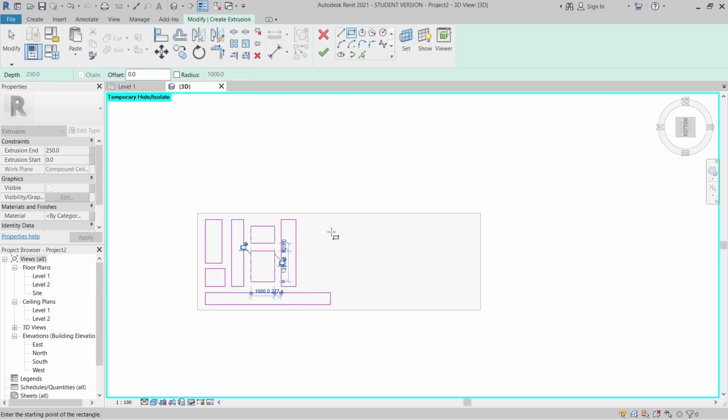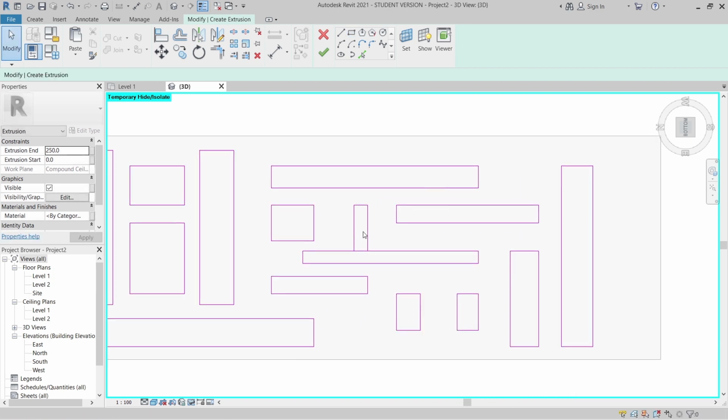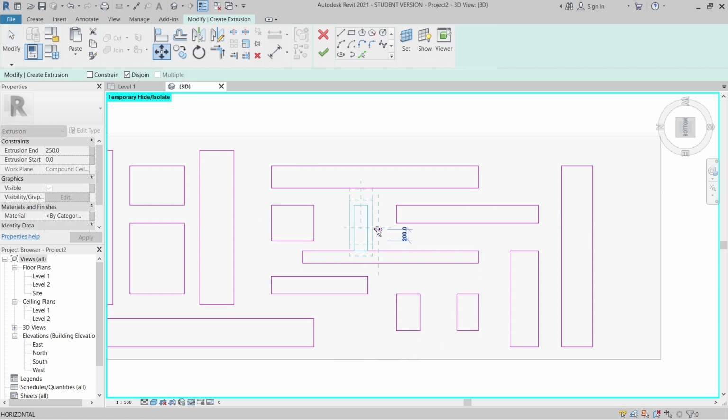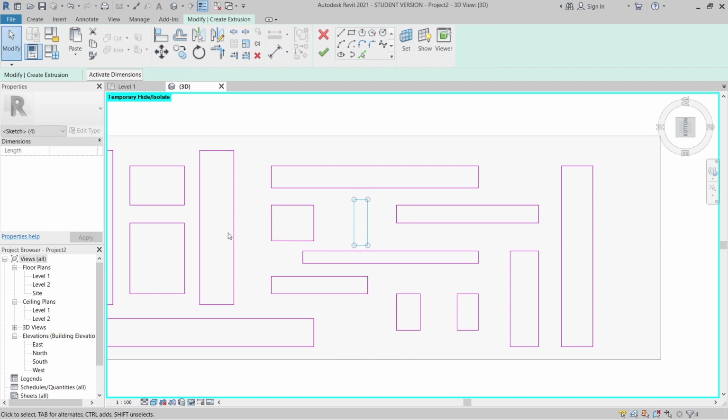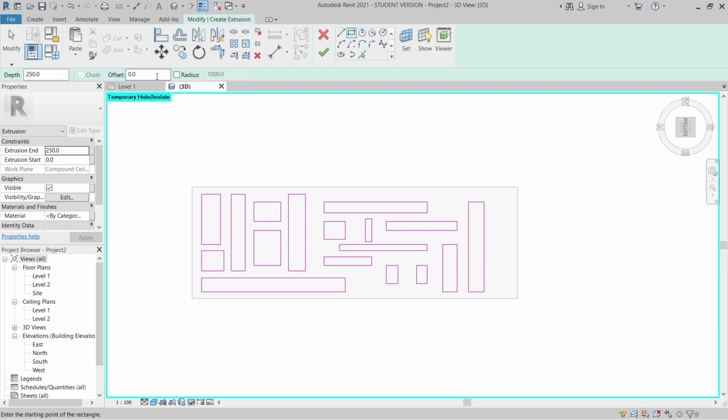Because it's a custom ceiling design, hit escape a couple of times, then I can check it out like this. Then I need to move. Once I've done that, I need to create boundaries first. Go to our rectangle again, then I will start to offset it by 100mm for thickness.